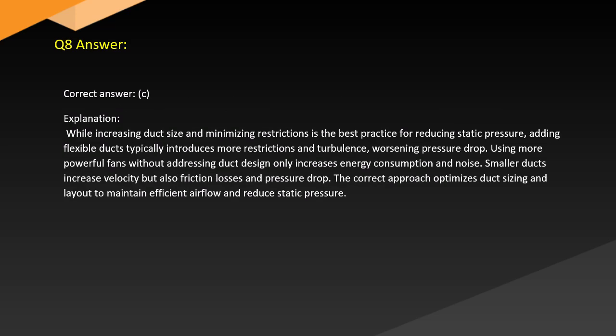Answer. Correct answer: C. Explanation. While increasing duct size and minimizing restrictions is the best practice for reducing static pressure, adding flexible ducts typically introduces more restrictions and turbulence, worsening pressure drop.